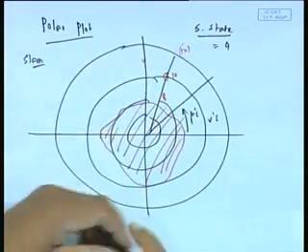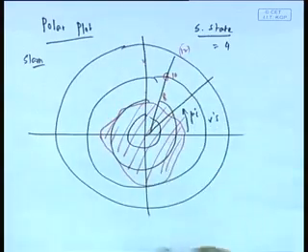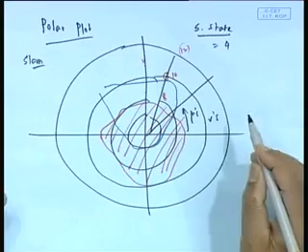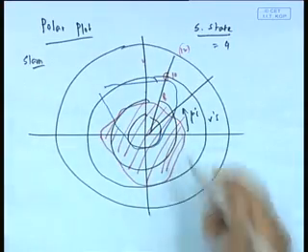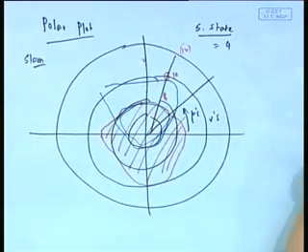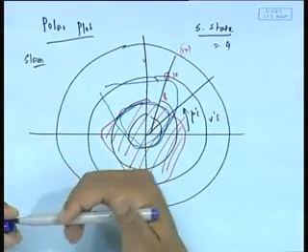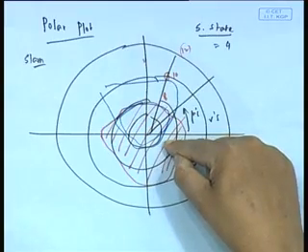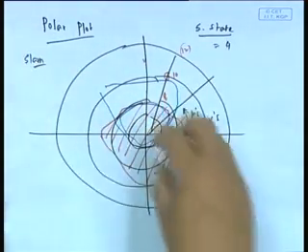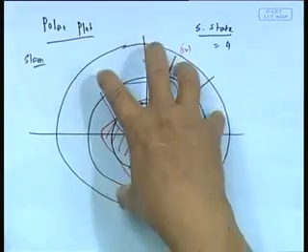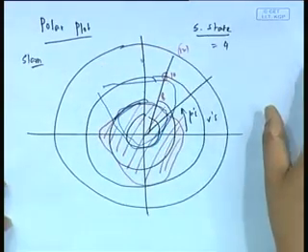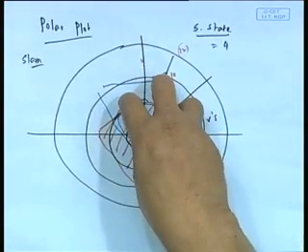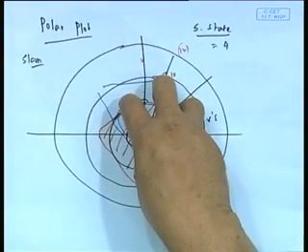Now, you will have to do the same for sea state 3. So, what you have to do is to put on that all other criteria. See, another criteria, roll for example, might be some other area. Then the two are combined only in this area, which is a common area to it. That means only in this area both roll will be less than 5 degree or whatever and slam will be less than 20 per hour. So, having done all that, you find a common area. This common area as a percentage of the total area would give me the merit, that means the merit of the design for that sea state is so much percentage. That means so much percentage of time, that is you can say performance index.